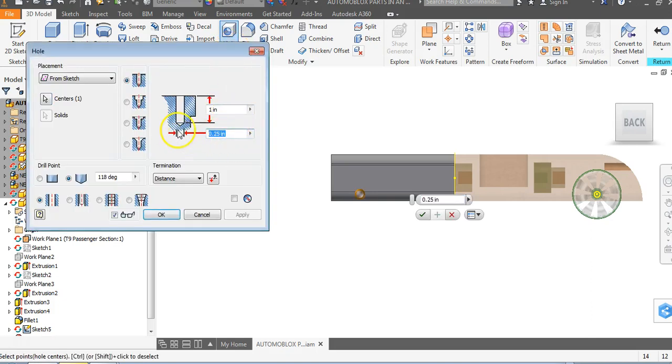And the hole diameter, all I have to do is type hole, it's case sensitive, hole, DIA, and then up here at the top, I'm going to type hole depth. And now we have the exact same hole diameter and the exact same hole depth as what we saw down here. And I'm going to go ahead and go to OK.